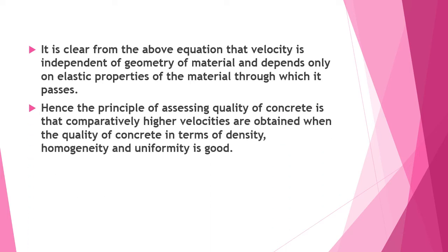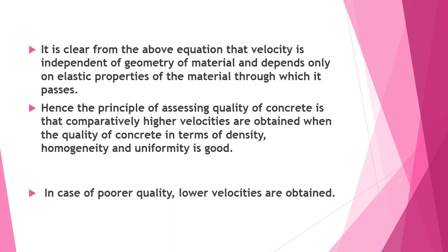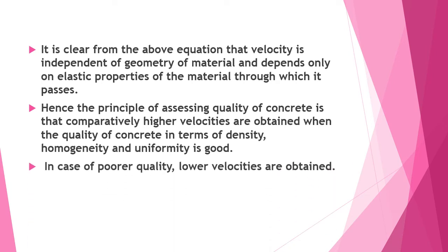Hence, the principle of assessing the quality of concreting is that comparatively higher velocities are obtained when the quality of the concreting in terms of density, homogeneity and uniformity is good. In case of poorer quality, lower velocities are obtained.